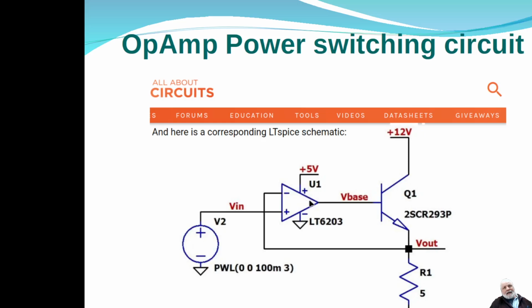But the op amp is going to provide, like I say, several hundred milliamperes of current if you want to drive a BJT. And the input current, the current coming in based on Vin over here, is going to be basically nothing at all. So if you have a microcontroller or whatever over here driving this op amp, you don't have to worry about any current in at all to activate that. The op amp is going to take care of the current to operate the transistor.